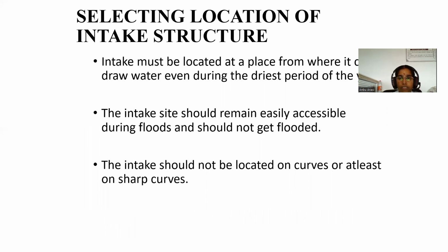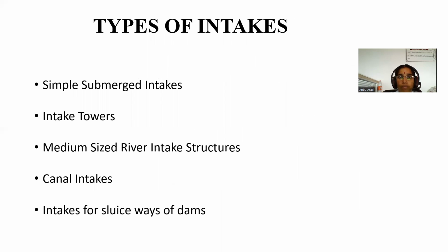Intake must be located at a place from where the city can draw water even during the driest period of the year. The intake site should remain easily accessible during floods and should not get flooded. The intake should not be located on curves, or at least not on short curves.